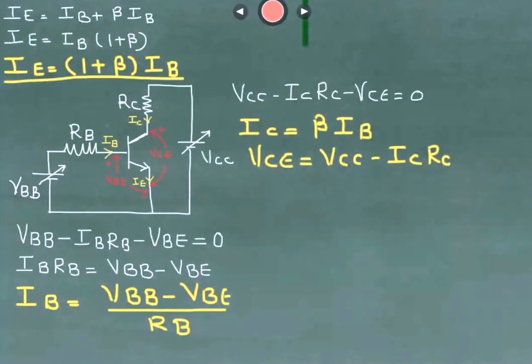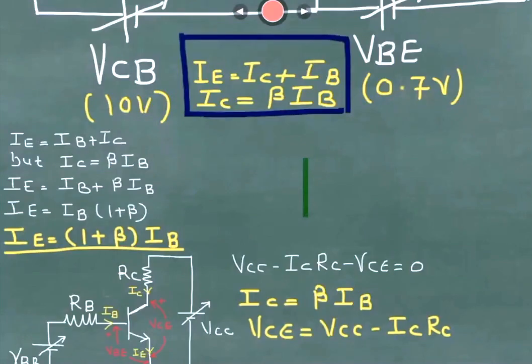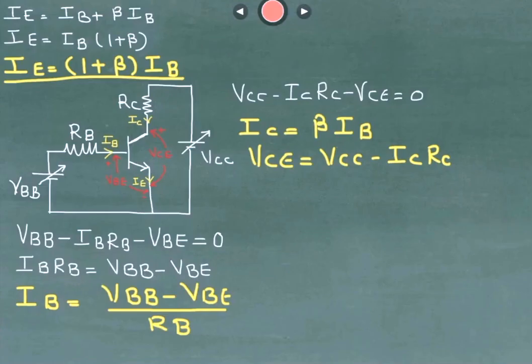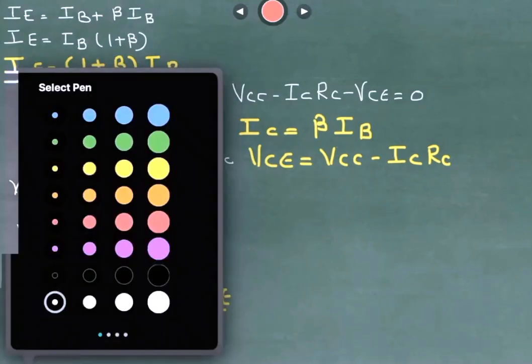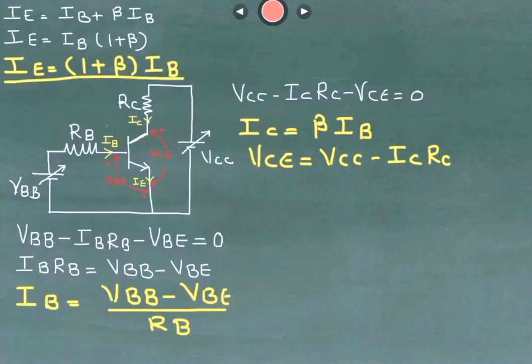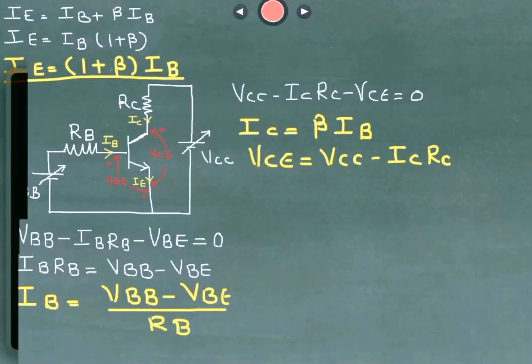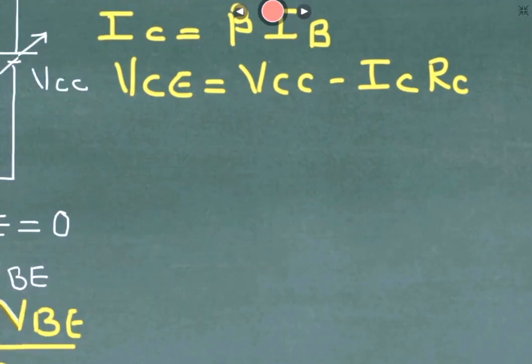Now if you see all these things combined, you will need to know one thing regarding this topic. Whenever a circuit like this is given, assuming all the component values are given, you need to first find the value of IB, then the value of IC, and then the value of VCE. So let us do one small exercise over here, and let me see whether you understand it or not. There are two conditions that you have to check. Let us see the above equation.